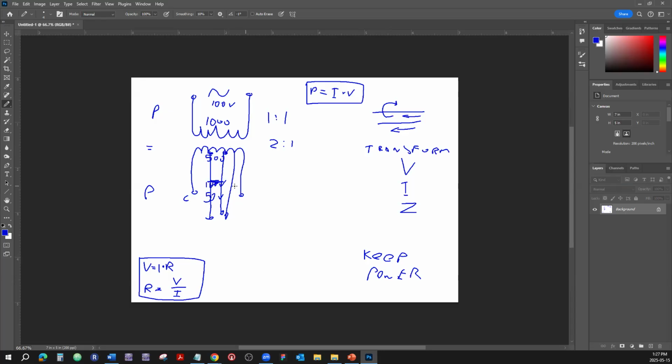How can we use this? Well, in audio, there are different types of transformers. Some of them are power transformers outside, big boxes, powering up the neighborhoods with the power service. But also there are certain audio transformers, and some of them are constructed in a way that they are called impedance matching transformers. Since they transform impedance, we can use them for impedance matching.